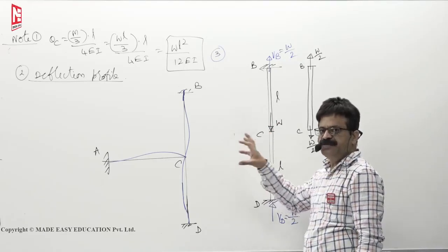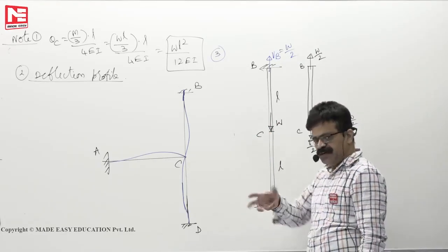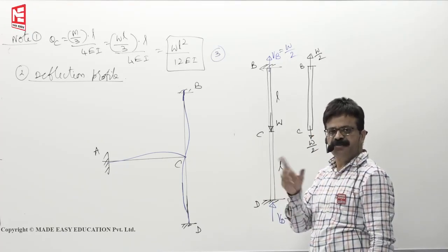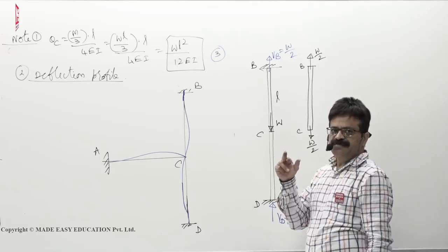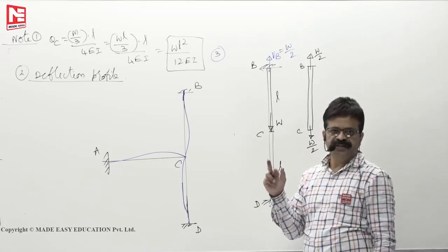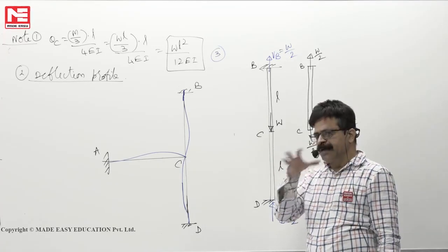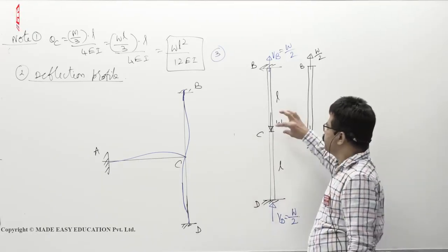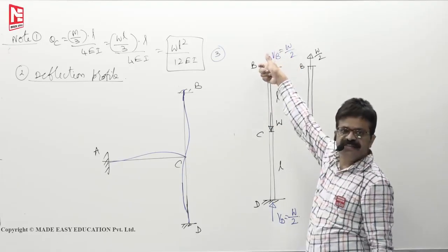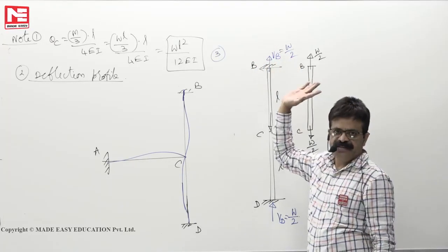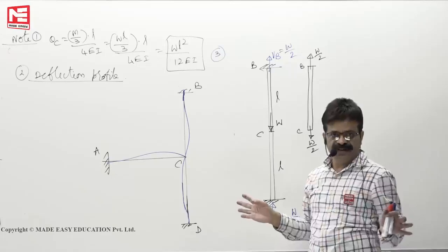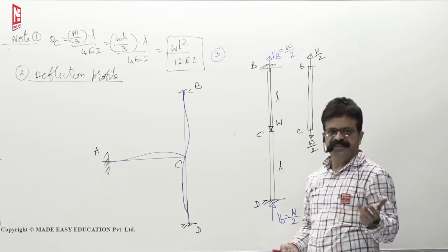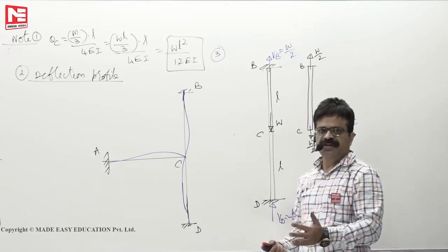Sagging bending moment positive, hogging bending moment negative. Clockwise rotation, clockwise moments positive. Anti-clockwise rotation, anti-clockwise moment negative. When we say clockwise, anti-clockwise, you are not worried about the bending moments. Then simply moment M you apply, same direction if it is transferred, positive, opposite, minus. Whether it sags or hogs, we will not worry. Okay, such issues, the assumptions and how BMD should be drawn.